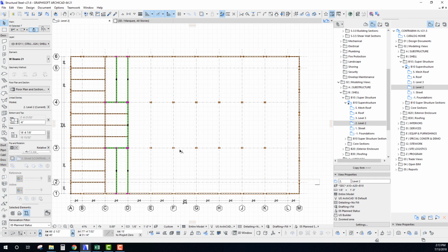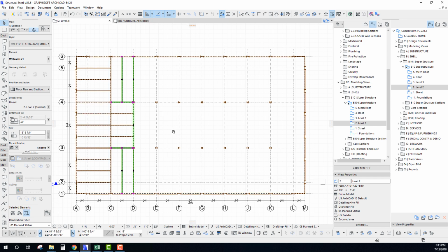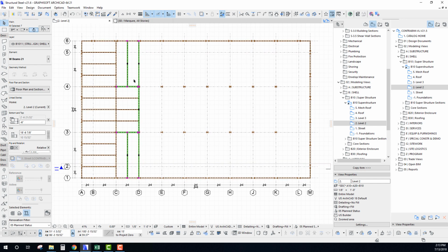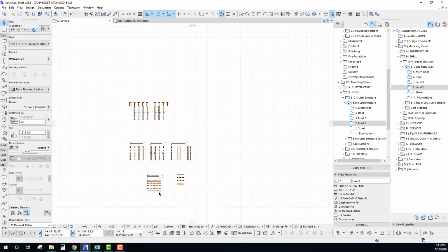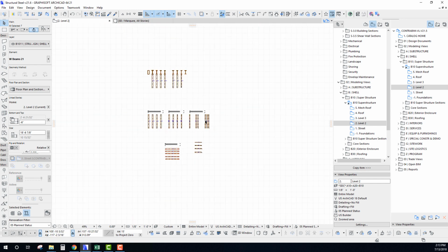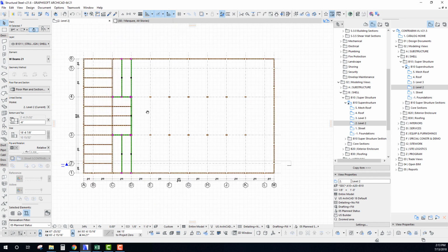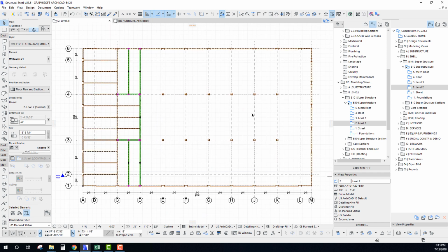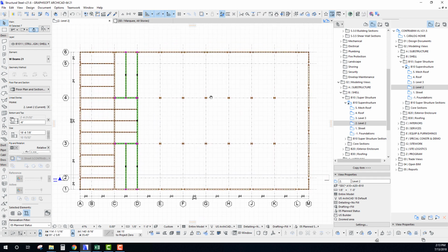And in a commercial building like this, typically you'll have some sort of core in the middle, or it might be set to the outside. But wherever you're going to have your core and your stairs and all of your vertical penetrations through your building, that's really where you're going to need to do a lot of detailing out with some of these smaller support beams around those openings. And so in this case, maybe we'll fill that in as we go.